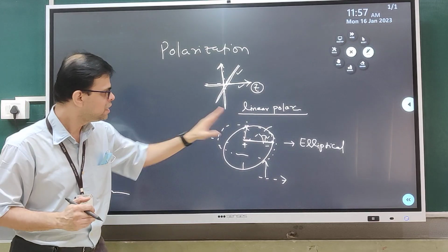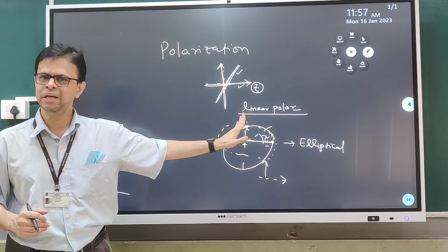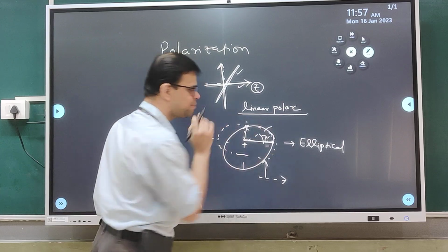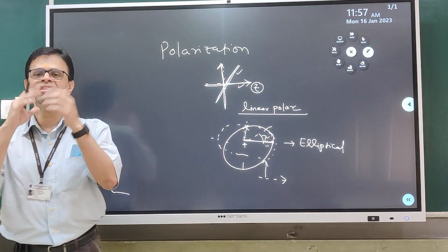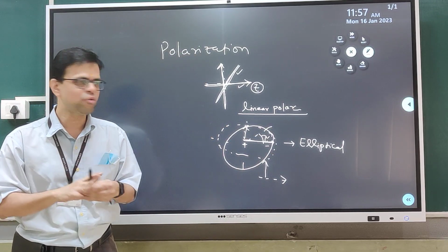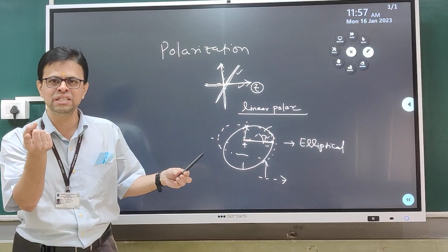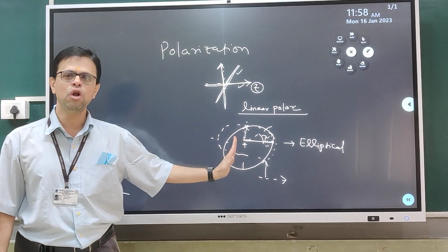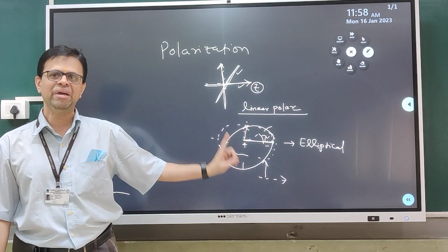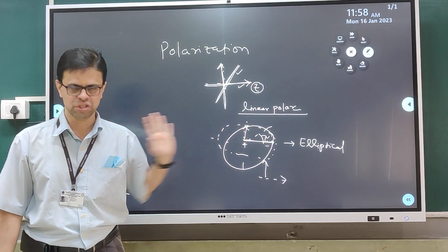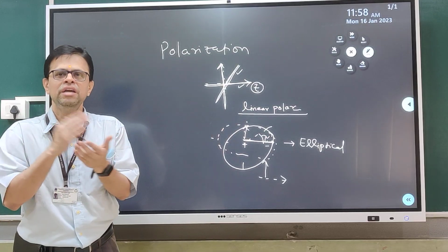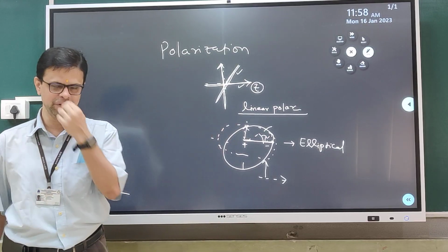It may be minimized at some angle, depending upon the ellipse angle and the magnitudes of the two axes of the ellipse. But different angles mean a mismatch of the incident polarization against the antenna polarization. So at different angles, you will not come across a situation where the signal is completely lost. So elliptical polarization is better if I have a multipath propagation effect.